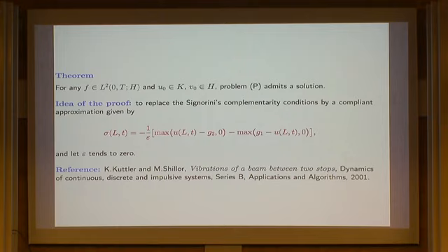And of course, the smaller epsilon, the smaller the penetration, so we get a more accurate approximation of the non-penetration condition. But of course, we need to choose also smaller values for the space and time discretization parameters. So from the computational point of view, this is a very expensive technique. And furthermore, at the end, we get a numerical approximation of the penalty approximation of the original problem. So we have two steps in the discretization.